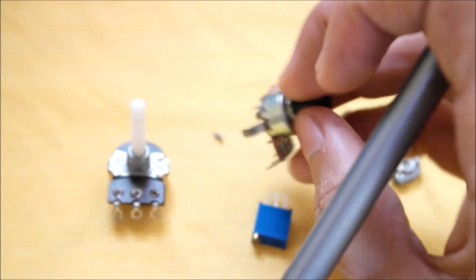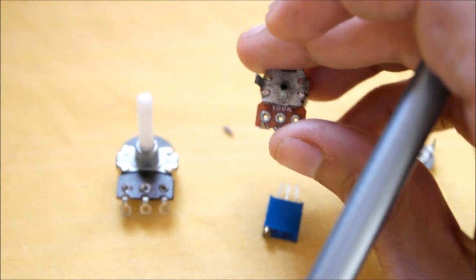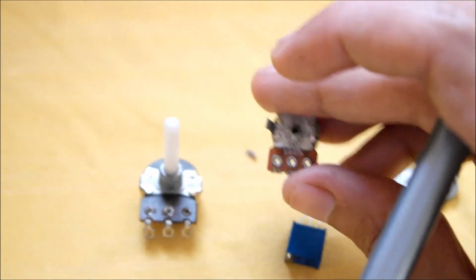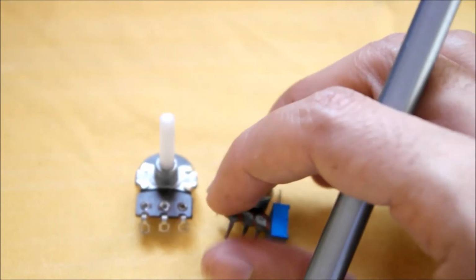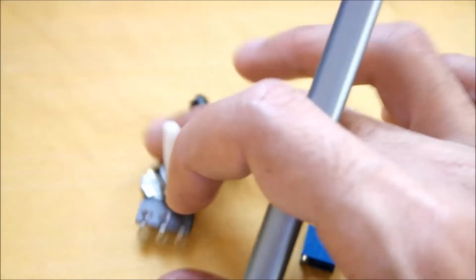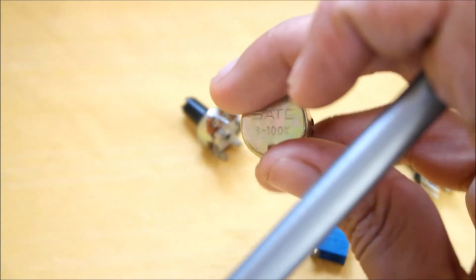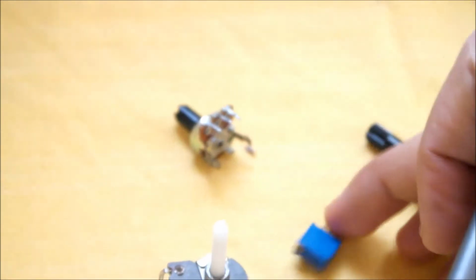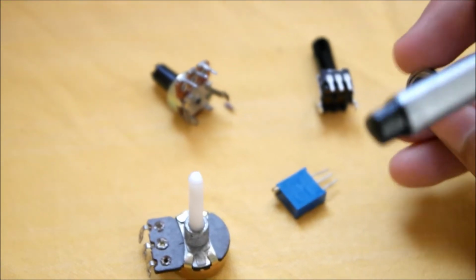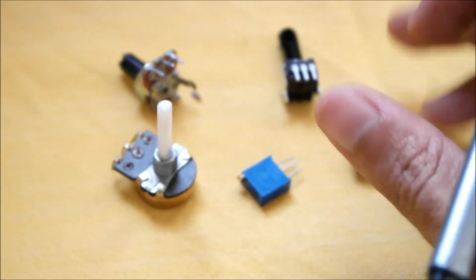And okay, so how to read a potentiometer? Generally, when you go to the shopkeeper and ask for a specific value of potentiometer, you can just check it at the back. It's mentioned over here. So a 100K potentiometer means the maximum value of resistance it can offer is 100K, and the minimum is always 0. This is also a 100K potentiometer. And this is 10K, I remember, and this is also 10K, and this is 10K. These are written somewhere in here. Just take a close look with a magnifying glass, you'll find it.